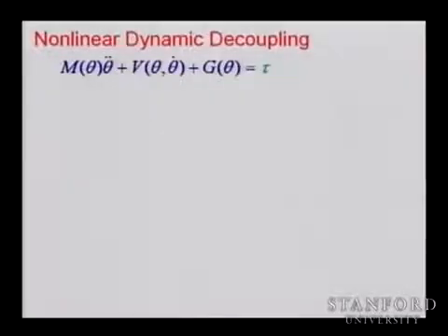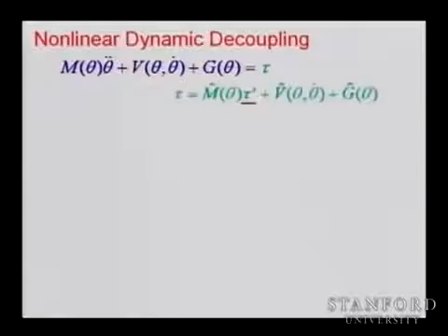So we take this model and we imagine that somehow, after a lot of identification work, we identified some estimate of the mass matrix. You know its structure, but it has parameters in it, inertial parameters and distances, that you don't know exactly, but you know approximately within epsilon. So you take an m hat of the mass matrix and you select a controller torque prime. So this is alpha f prime plus beta.